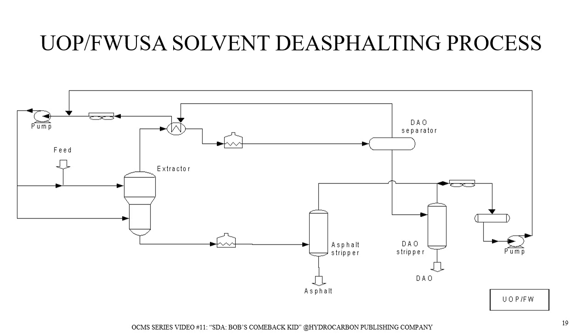The company also licenses ASCOT, in which pitch production is eliminated by feeding SDA bottoms to the coker. In this process, coke make is reduced compared to operating a SIDAC unit alone to treat vacuum resid. Furthermore, heat integration provides energy savings.